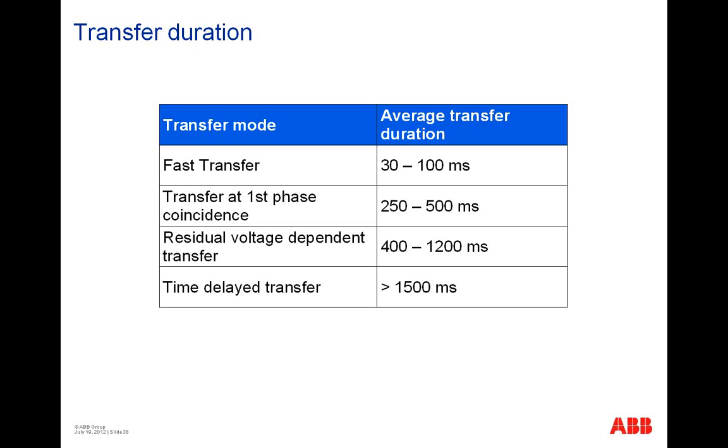And a good breaker, well, we said worst case the closing time is 60 milliseconds. So we calculate all together: 20 milliseconds for the protection relay to detect the failure and give the information to the HSTD, meaning the command, please perform the transfer. 10 milliseconds for the HSTD, then we are at 30 milliseconds, and 60 milliseconds for the breaker. Then we have 90 milliseconds.